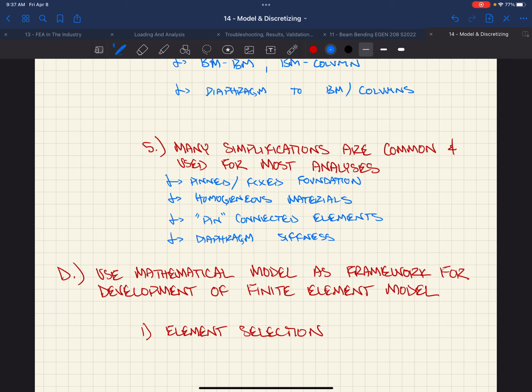And you say you have a shear wall here, a shear wall here, and a shear wall here, right? 2 bays, 3 walls. Say this is L and this is L, what do you take as the shear force on that? Half of the total shear force, right? That's what I would say. Depends on the stiffness of the diaphragm. Okay. I do not like that assumption. That assumption happens all the time. I do not like that assumption. That assumption assumes that you literally have a pin at the center, right?